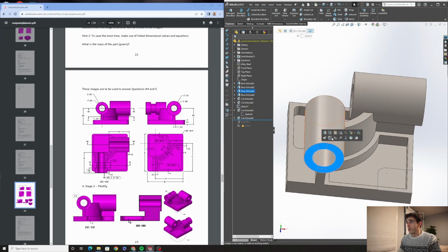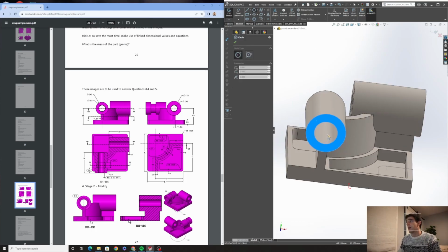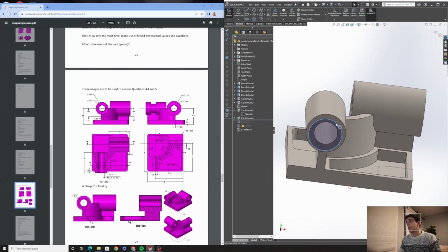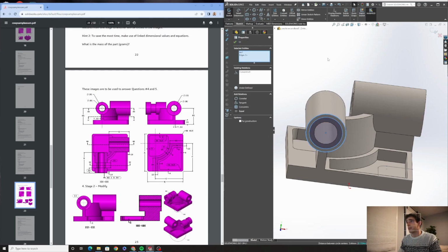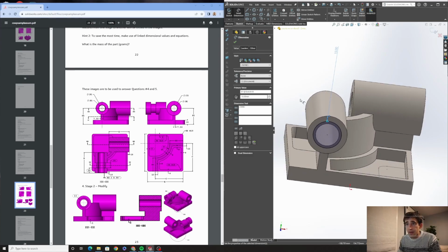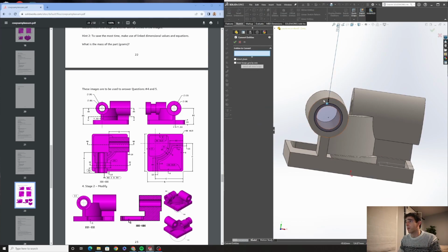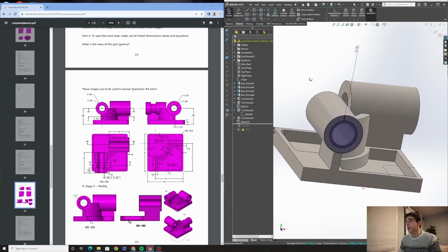What I'm going to do is sketch on this front surface. Let me see if I can find where that diameter is. Oh, it's listed here, section KK. It's a diameter, it's an offset of 10. I'm going to draw a circle. Would have been great if I snagged that auto relation, but I didn't. That's okay. 10 from that outer surface, and then to create this cut, I'm also going to grab this outer edge here.